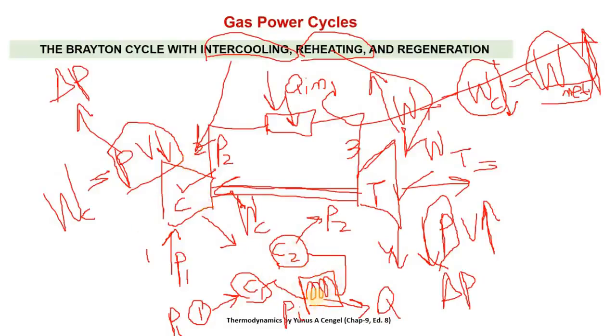So now what will happen? The result is that we have increased the pressure in two steps instead of one single step, and in between we have used an intercooling process. When pressure was increased here from 1 to I, some intermediate pressure, temperature was also increased, volume was dropped, but now it is cooled here, so volume will drop, right?